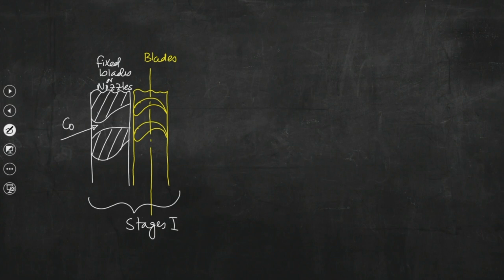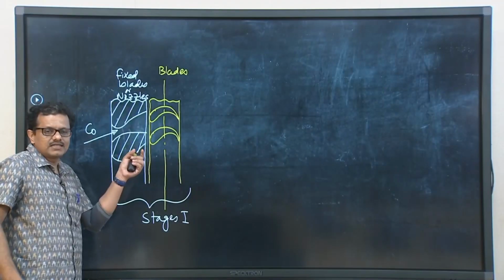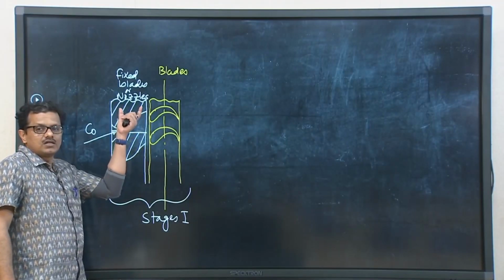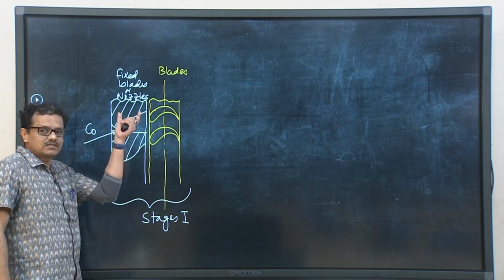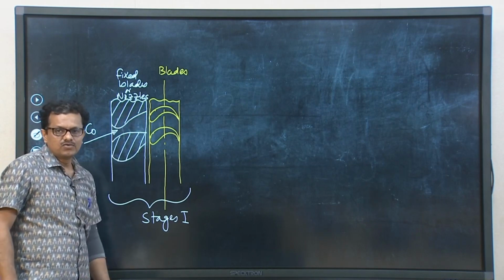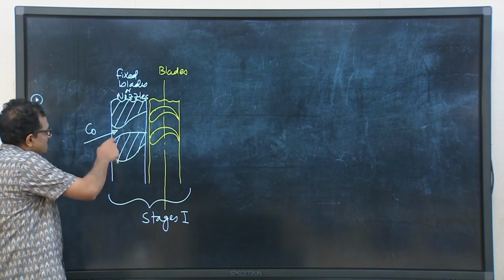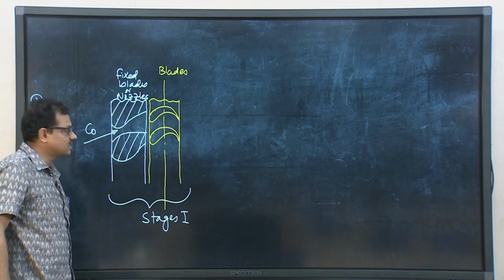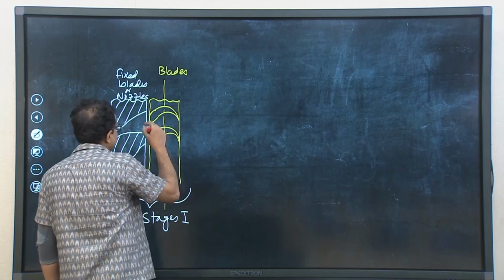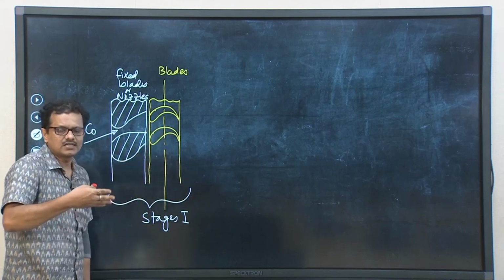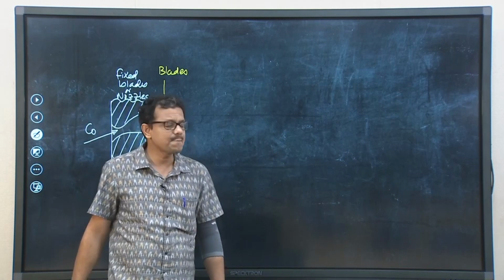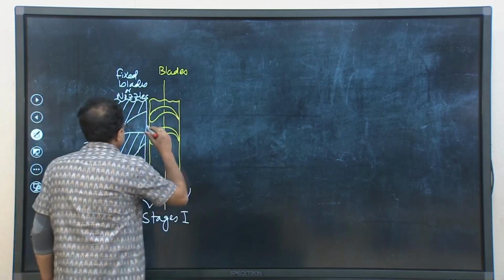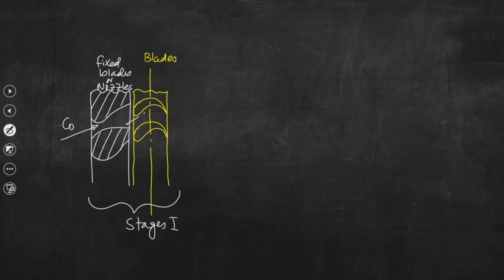So, steam which is coming out from the turbine now is entering into the flow nozzle, and as I said, that steam turbine is basically an assemblage of a row of fixed blades and a row of moving blades. So, that steam which is entering into the first row of fixed blades or nozzles is essentially coming out with a higher velocity, and that is how the nozzles are designed, and that velocity is, say, this is C1.